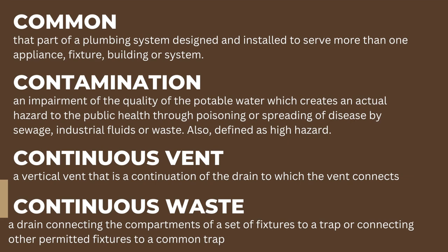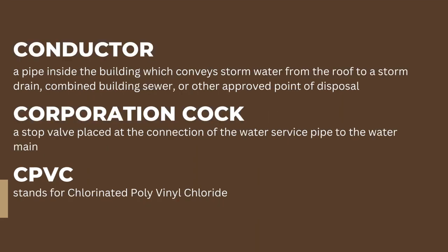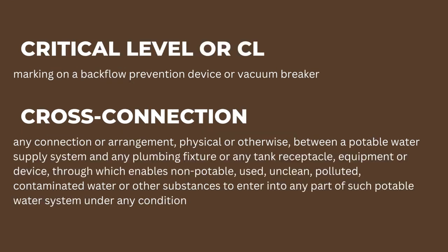Conductor: a pipe inside the building which conveys storm water from the roof to a storm drain, combined building sewer, or other approved point of disposal. Corporation cock: a stop valve placed at the connection of the water service pipe to the water main. CPVC stands for chlorinated polyvinyl chloride. Critical level or CL marking: a marking on a backflow prevention device or vacuum breaker.